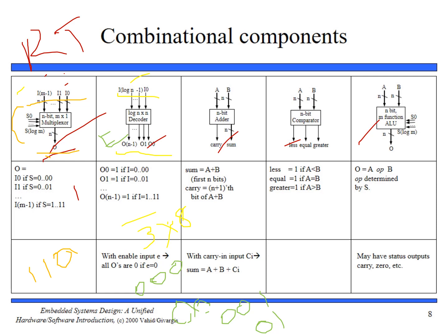Now moving on to our adder. So an adder adds two n bits binary data inputs A and B, generating an n bit output sum with an output carry. For example, a 4-bit adder would have a 4-bit A input, a 4-bit B input, a 4-bit sum output and a 1-bit carry.